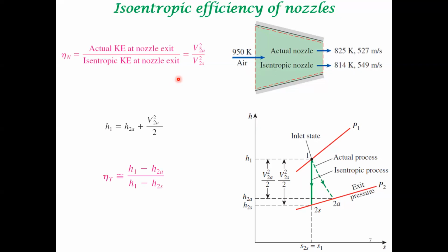Again, here, of course, the kinetic energy differences play an important role. Therefore, the enthalpy balances will include a difference in kinetic energies. So this is the inlet stream. Kinetic enthalpy is this one. The outlet stream enthalpy is this, plus there is a kinetic energy term.